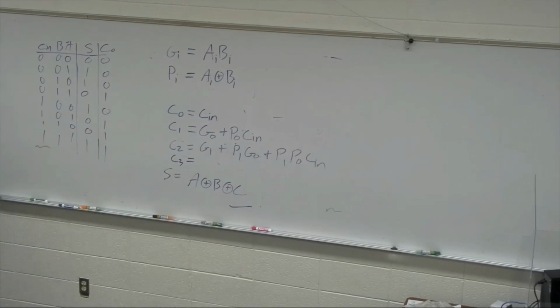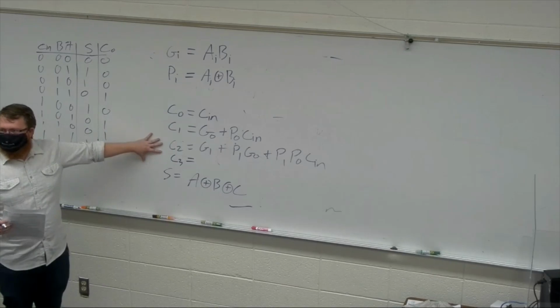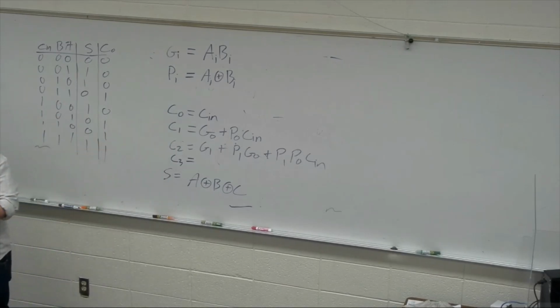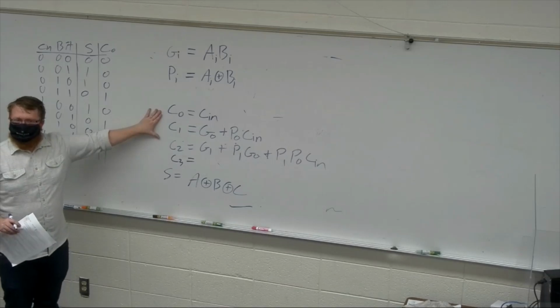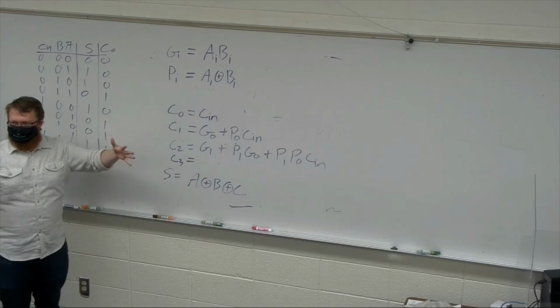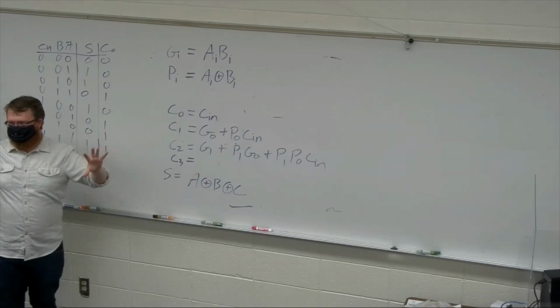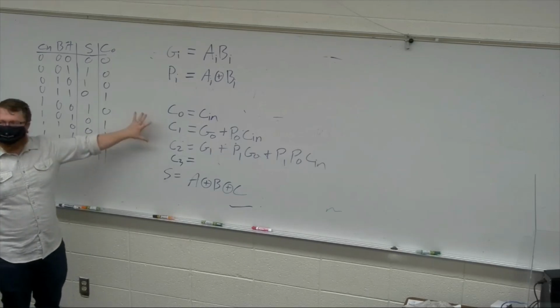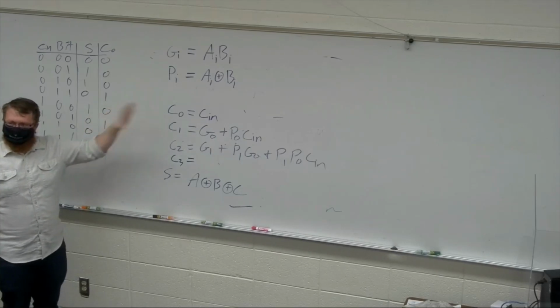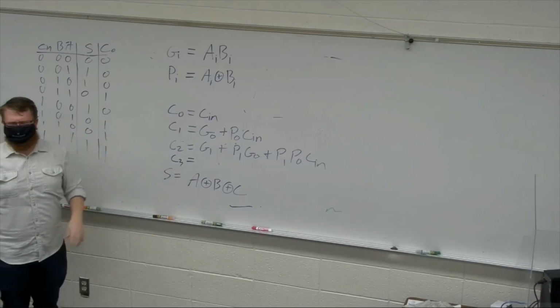Yeah. So you can, and they do very frequently, design these in 4 or 8-bit blocks, and then I will have a little bit of delay, right? So I'll have a mixture between the look ahead and the ripple. I'll have chunks of look aheads and then ripple through those look aheads. But still, regardless, it's going to be much faster to implement a 4-bit one of these and then ripple it through, right? It's 4 times faster or something.